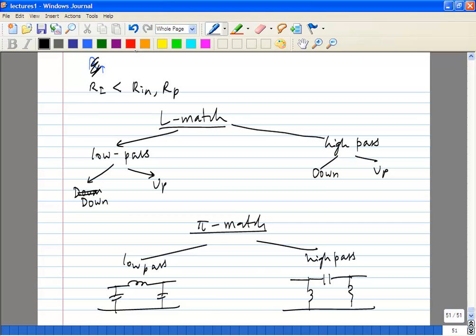In general, which would you prefer? Why? Capacitor gives a direct separation between the two. You would prefer a low pass because what? Sides. That's right. The reason you would prefer it is because you don't want two inductors. Remember, inductors are huge in any IC process, for typical values. We are looking at a few nanohenry and a few picofarad.